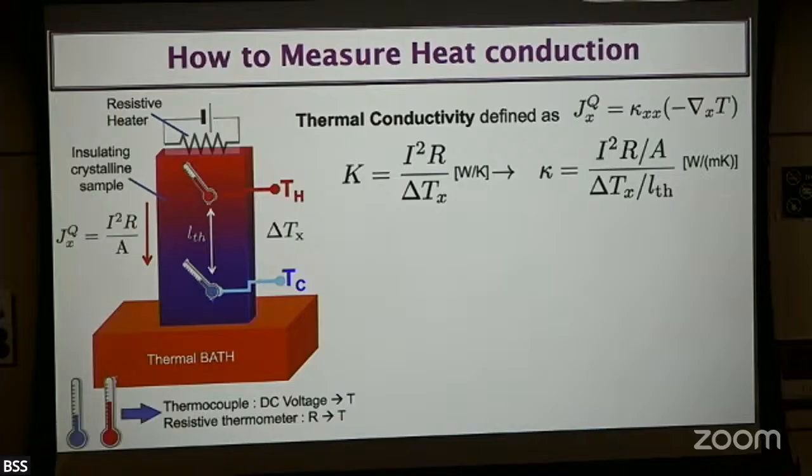Oh, yes, I'm also getting there too. How good a vacuum? So I give you a number, our measurement is at room temperature about 10 to the minus 5 to 10 to the minus 6 torr. And once you go down to low temperature because of the cryogenic, especially below nitrogen temperature, we are expecting it to be a lot higher than that. Yes, I will mention that.